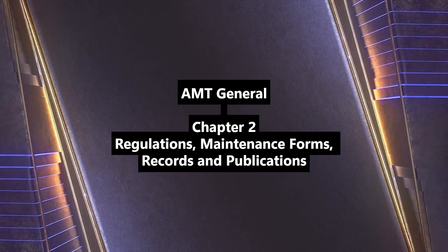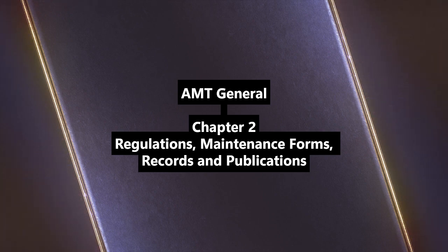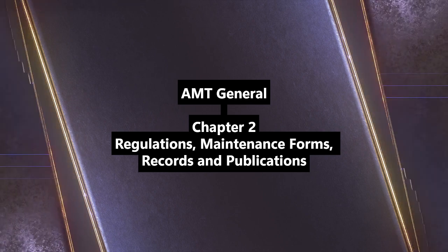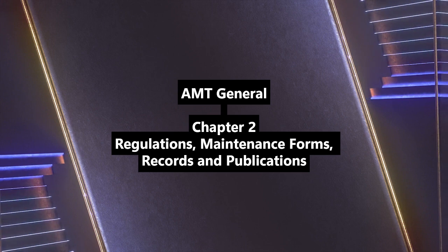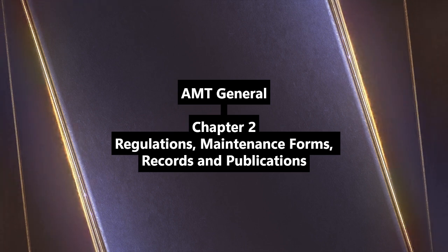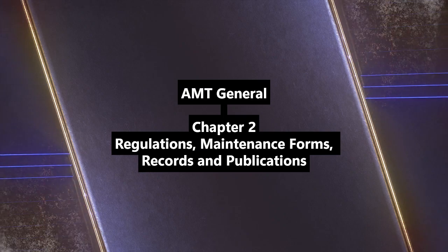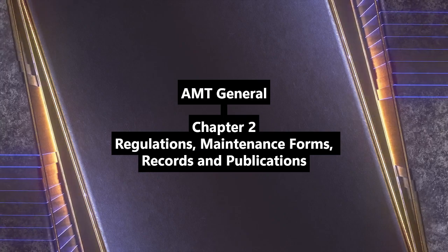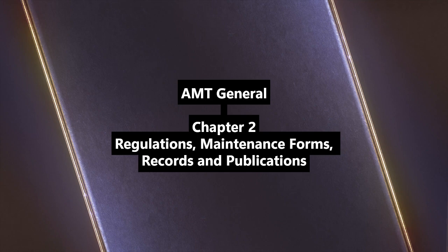What if you suspect a part? Immediately tell your supervisor or quality control. Segregate and quarantine the part until its status is confirmed. Contacting the manufacturer is often a good first step. AC 21-29 has more guidance. Okay, vigilance is key. Let's wrap up with some other FAA documents technicians should know about.